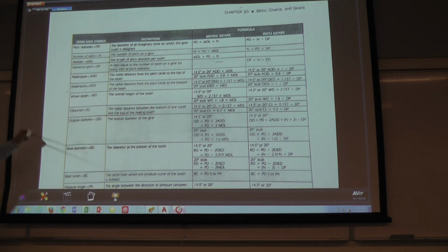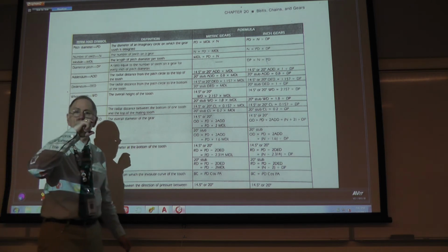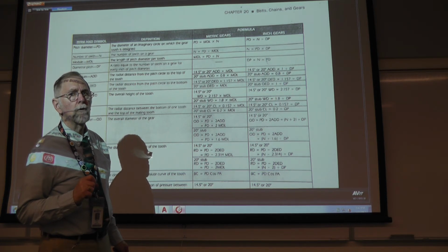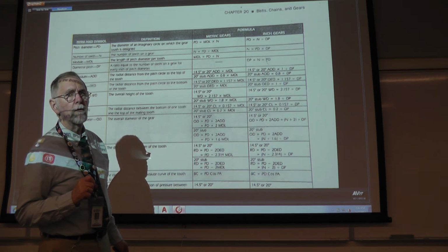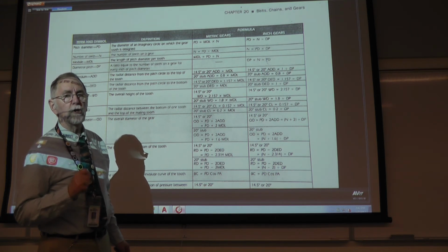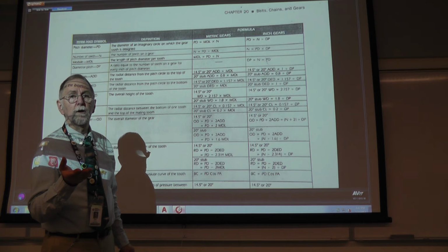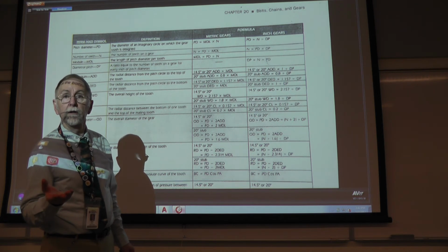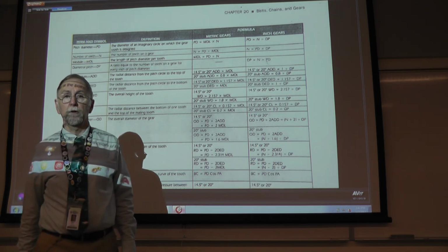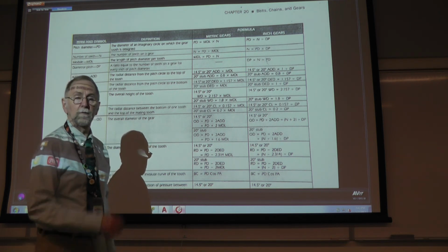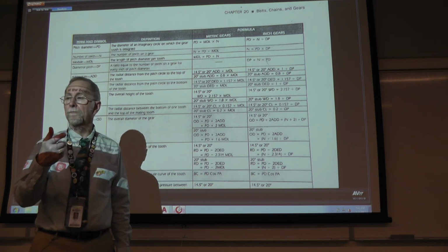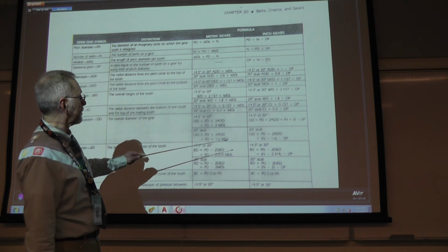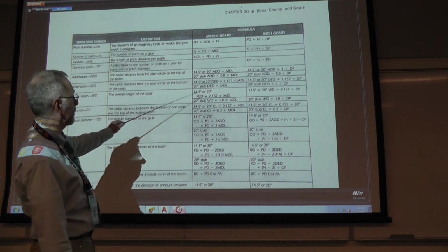The whole depth, which is the height of the tooth, yes, Pierce? So I remember you saying that, or maybe it was the presentation earlier, but 14.5 and then 20 to 22 are common angles for these. Right. You could see a 14.5 degree tooth form or pressure angle, or 20. So we're not going to see some weird number. No, you shouldn't see a weird number. It's standardized. Cool. The design has been worked on and works out for the standard sizes. Cool. Thanks.